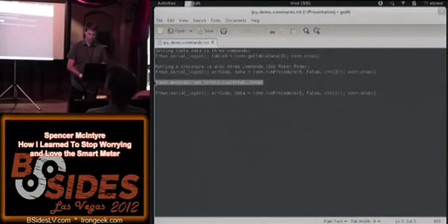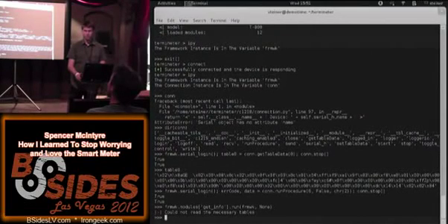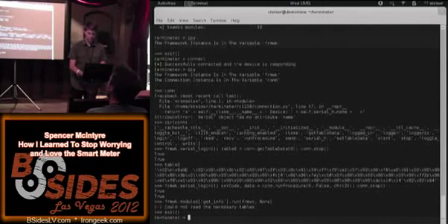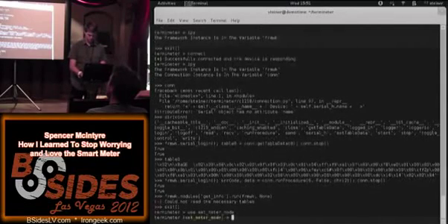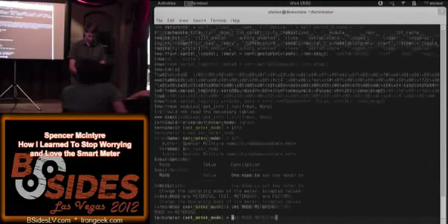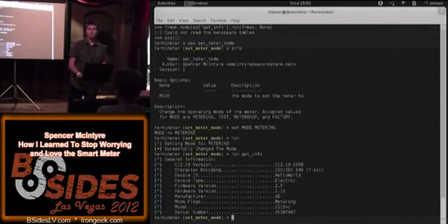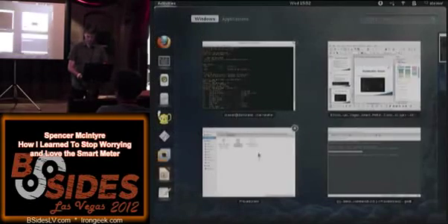Now we're going to run the get info module again to see if it's still reaching those tables. And it can't reach those tables anymore because the meter has locked itself. Those tables are no longer accessible because the meter's mode is in test. Now, if we change the meter mode, we can read the information again.